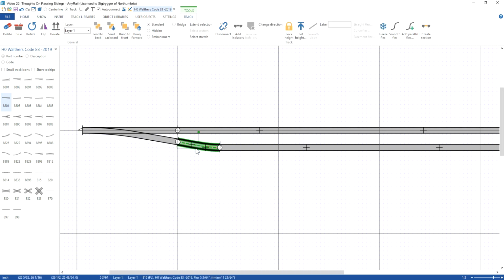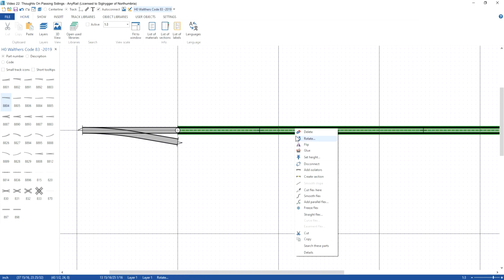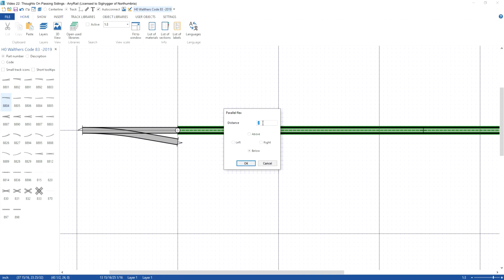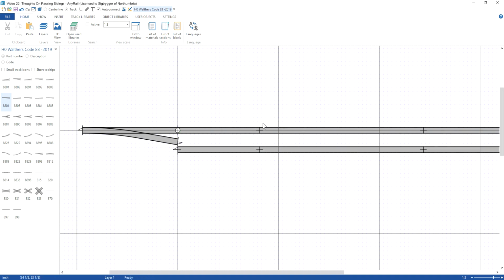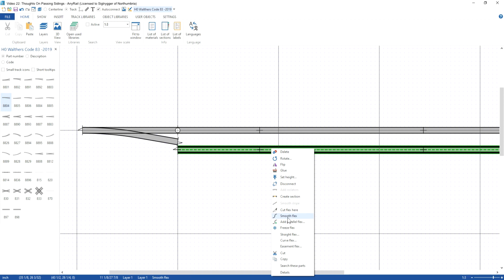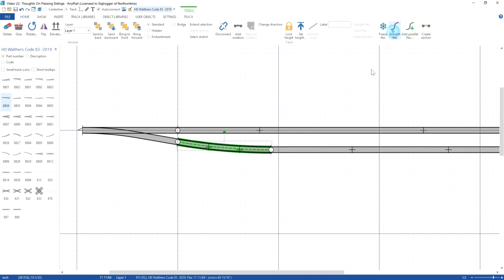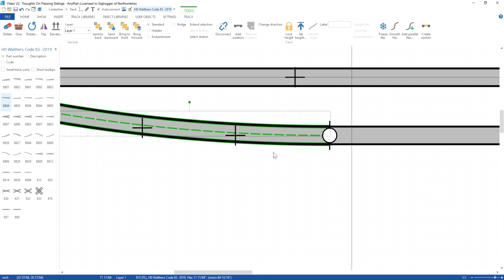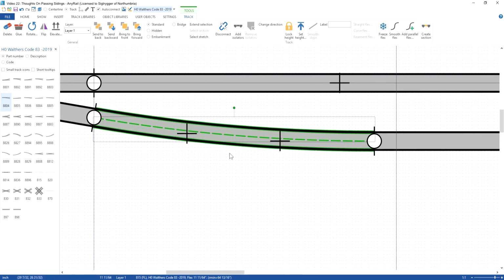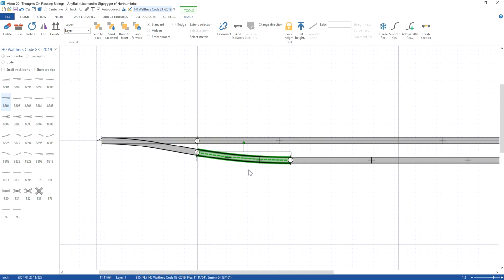And of course, you can do anything you want here. I can set this to any size that I want, meaning the distance between the tracks. I could say I want 2.25 inches. And then just do the same thing. Select a point out here. We'll cut it right there. We'll drag that up. Hit smooth. What do we got? Nice gentle curve coming in. And I can zoom in, and I don't see any evidence of an S-curve doing that.